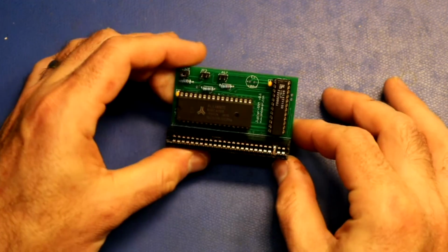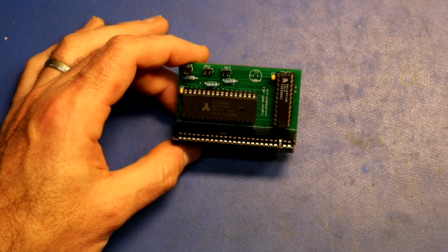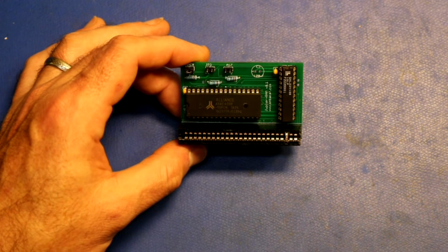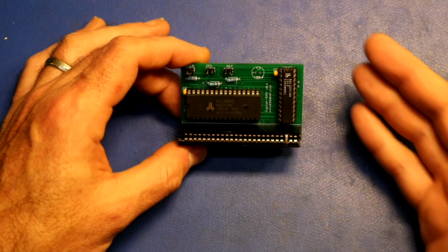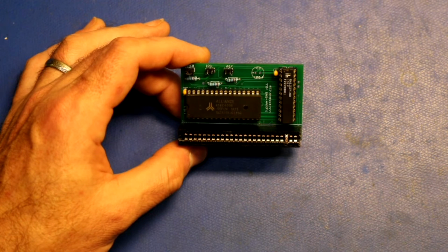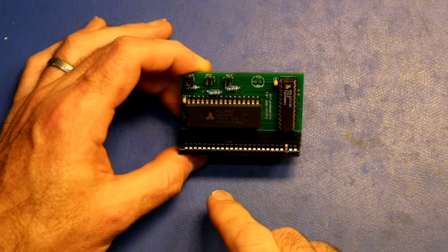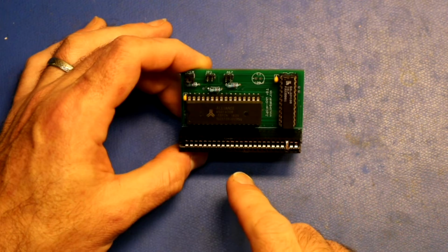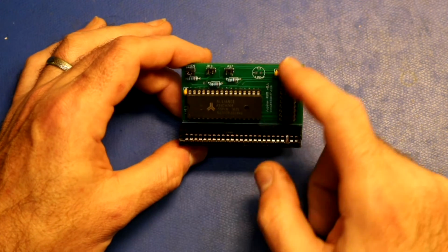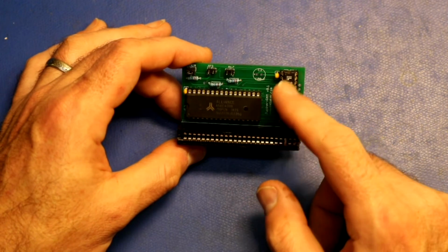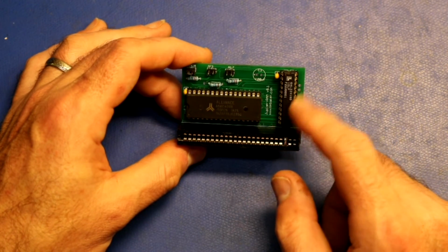So this first board here is a RAM expansion. The Jupiter Ace only has, I think, like 768 bytes of RAM for user programs, which is not very much. But you can easily add an additional 48K into 48K of unaddressed memory space. So what I have in here is a decent size RAM. I think I used an AS6C4008. And then I have a GAL22V10, my programmable logic device of choice, that handles all the addressing.